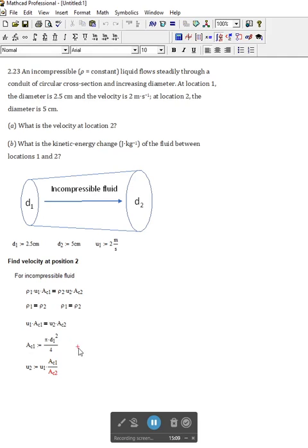And one thing I like to do whenever I do a calculation like this is check my values, make sure everything's right. So A dot C1. Now, how do I get a value out? When I defined an equation like this, AC1 Shift colon is defined as pi d1 squared over 4. What I do to find the value is I type A dot C dot 1 and then just a plain equal sign.